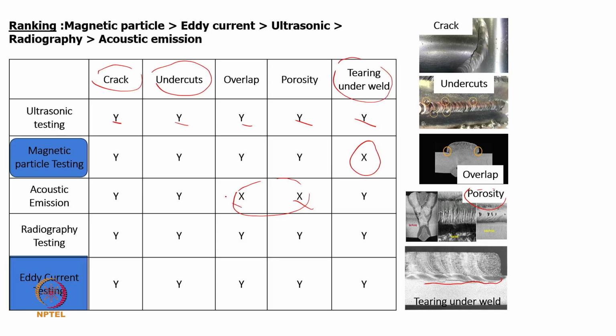So, these points are also important to keep in mind. As I mentioned, eddy current cannot be used for non-conducting material. Or, if it is required, then we need a very different kind of material to be painted on the surface. So, overall, if we have good knowledge, we can really choose a good technique accordingly. Or at least, if we do not have a good technique available, we have some technique, and we can add on to it, and we can use our own creativity.